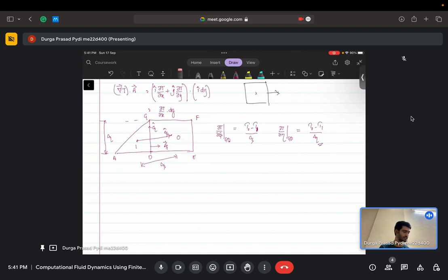Or if you were to follow the Taylor series, ideally it should be something like along the eta direction, you should have something like tg minus td by delta eta. Following the same notation, del t by del epsilon is essentially t0 minus t1 by delta epsilon. Similarly, along the eta direction we can write it as tg minus td by delta eta. The only problem with writing it this way is we do not know the values of tg and td. We only store the values of temperature at the cell centroids and not at the vertices.